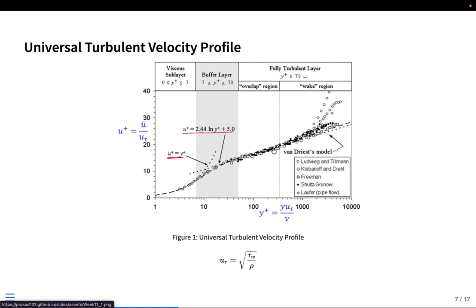So this is what they have observed, and they have non-dimensionalized these velocities in terms of u tau, which is a quantity which relates to the wall shear stress. And then we have a local Reynolds number given by y plus, and in this non-dimensional quantity, across different sets of experiments, the following correlations are developed by fitting the data between u plus and y plus. How do we use this u plus and y plus?